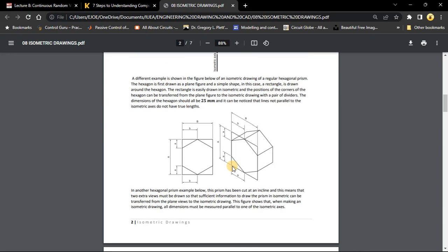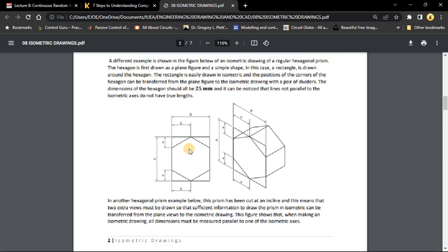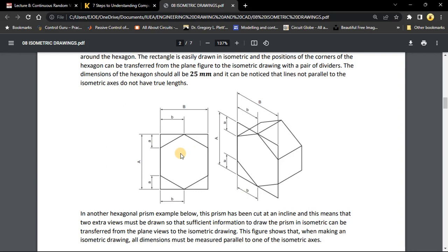length of the object. So in so doing, what we have to do is to project all distances to a certain cuboid, because a cuboid is the simplest object we can represent in an isometric drawing, because we would actually take the true length, true width, and true height to make that cuboid.